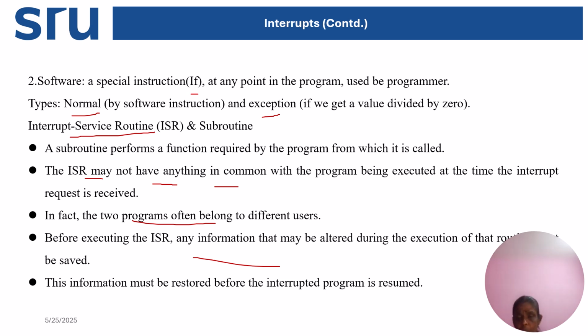Before transferring to the ISR, that means before starting off the ISR, we have to think: suppose the main information is going to be changed or altered, that information should be saved temporarily, and at the end of the ISR, while returning to the main program, whatever information was saved temporarily should be brought back, and then it will continue the main program.